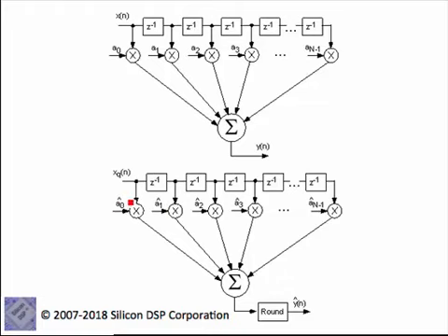Typically the coefficients will be represented by a certain size word length along with a number of bits associated with the fractional part. Many times the coefficients are normalized to all be less than 1, so you can represent them as a 16-bit number, for example, and with a fractional part. And you can also allocate a certain number of bits for the integer part. And in Capsim we support the specification of a word length along with a number of bits for the fraction, and the remainder of the bits, for example, used for the integer part and of course sign and so forth.